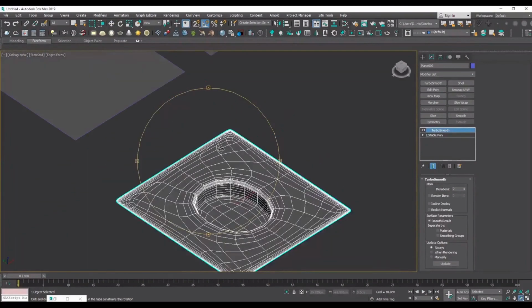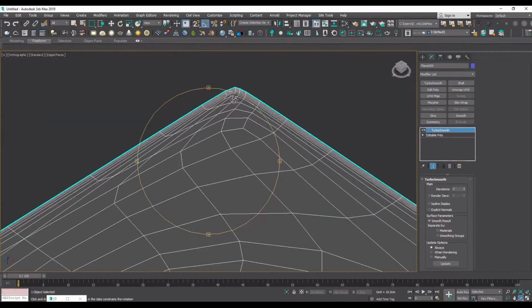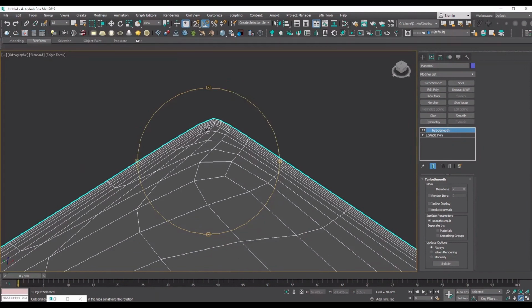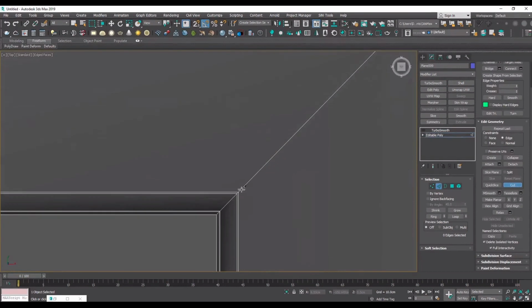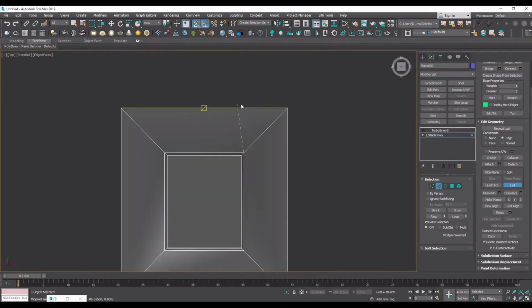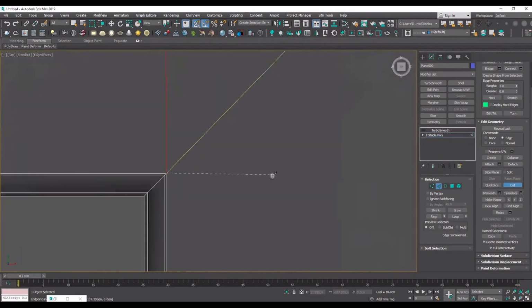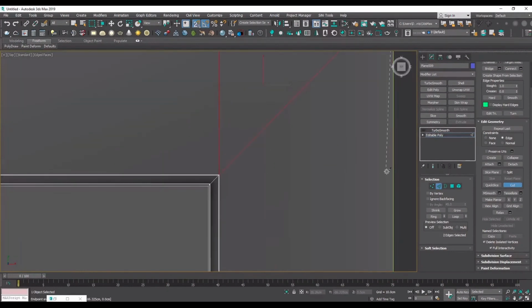It is in fact limited and not circular, but again it's completely messed up. If it's not the way to do it like this, you might ask how to fix this then. I say we should first delete the lines by double clicking and removing. Instead of using this diagonal line, I add 2 edges using the cut command and manually trace the straight lines of our box and connect them to the corner.